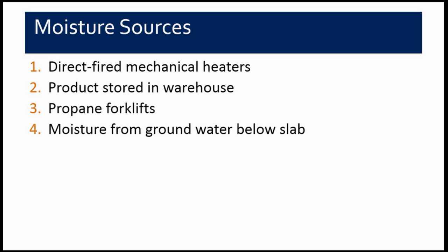The problem is, not only does it bring the heat into the interior, but when you burn natural gas, you release moisture. About 2.25 pounds of water is released for every 1 pound of gas. So there's a lot of moisture. It also releases carbon dioxide. But in these large warehouse spaces, they have carbon dioxide monitors, and if they get too high, they have exhaust fans that kick on, and that helps reduce it. But most of the time, those exhaust fans never kick on. The carbon dioxide does not build up to dangerous levels.